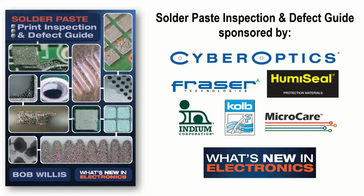Is there a way to use paste exceeding suppliers' recommended stencil life? Of course, with the greatest respect to my paste suppliers, if a paste is still printing and printing well, and you're getting good print characteristics out of it, I do not see any reason why you can't continue to use it.